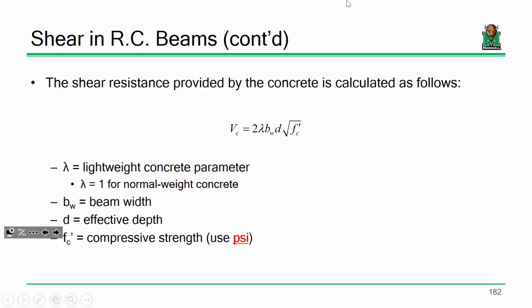What I'm saying is that under shear, there are changes, but they aren't appreciable enough. In other words, however the beam is proportioned, its shear behavior doesn't really change. It's just going to fail, and when it fails, it fails quick. So that's why we can just cap off the phi at 0.75. Did I answer that? Everybody else okay with that?